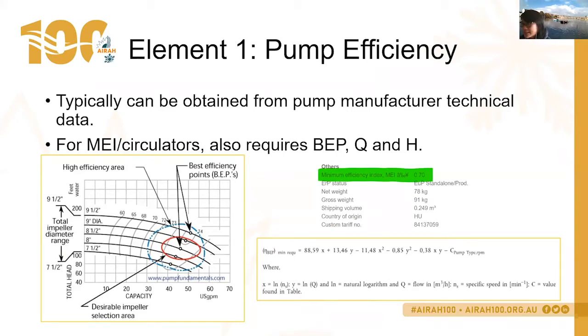As you can see there, it's based off a number of constants, which looks at your flow rate, and it looks at your pump type as well. And if you go into the document itself, you see lots of tables that tell you what the specific constants to apply to this formula are.